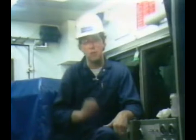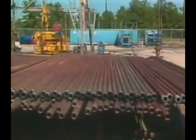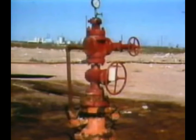As with any completion operation, thorough job planning is a prerequisite to a successful perforating procedure. And the first step in planning a perforating job is to accumulate the necessary data. Of primary importance is information on the well tubulars, specifically casing or liner size and weight, tubing size and weight, packer type and pressure limits, wellhead connection, and pressure test specifications for tubing, casing, and wellhead.